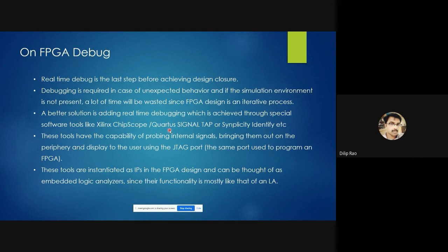You need to identify the signals you intend to probe. They are very limited because, by adding FPGA debug, you are actually adding logic overhead to the existing design. You need to handle it carefully because there is a possibility that because of the added debug overhead, the actual design may no longer work. So the debug logic that you have added becomes totally useless. There are several aspects that you need to balance there.